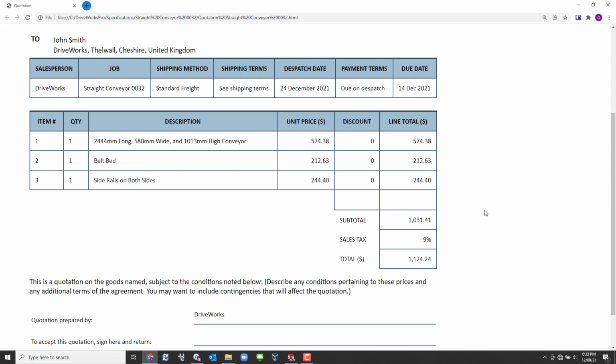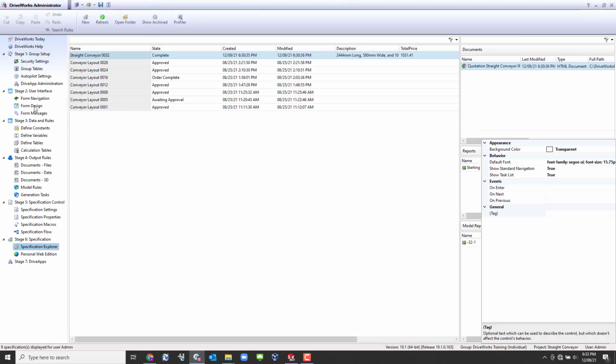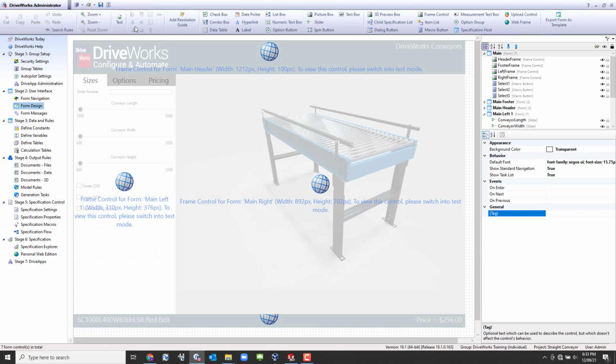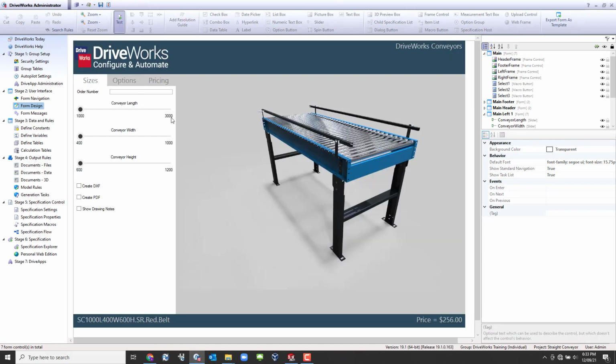So like with the rail lengths, would you get the limits for the length? Yeah, so you can do a couple of different things there, right? You can set limits, which we find most customers are doing off of their equipment, right? If it's a piece of sheet metal and our press brake can't bend something longer than this, that's the cap that you can set, or it goes up to two different pieces of metal, right? And you can do things like that.